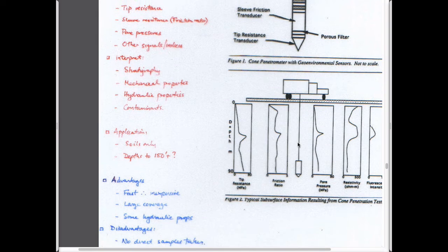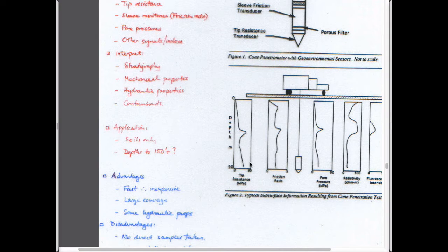And so what you get are profiles of how the force at the tip changes as you push it into the ground, how the friction along the side of the tip assembly changes, and also the magnitude of the fluid pressures that you generate.